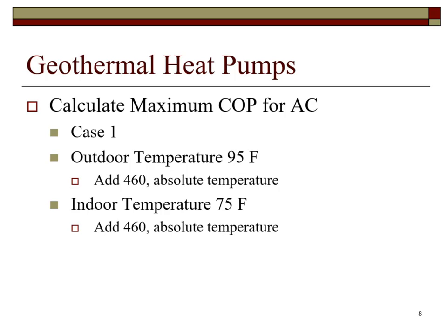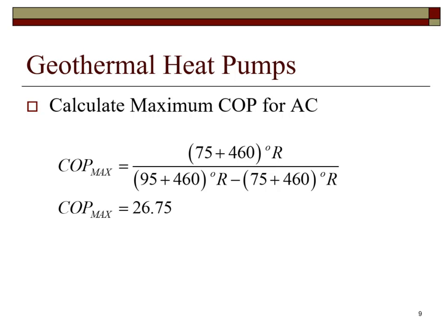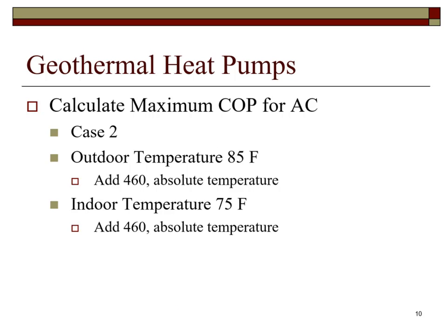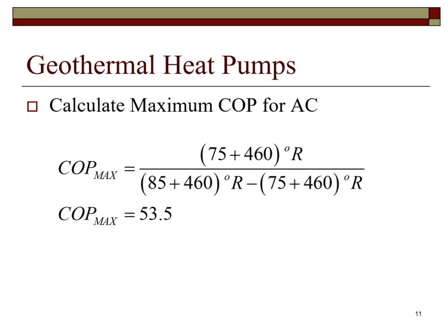Let's look at the condition of an outdoor temperature of 95 degrees Fahrenheit and an indoor temperature of 75 degrees Fahrenheit. The maximum COP is 26.75. With the outdoor temperature lowered to 85 degrees Fahrenheit, the COP is now 53.5, almost twice as efficient.